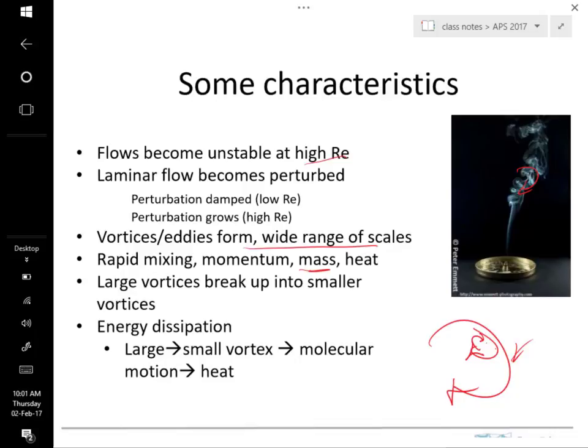And so what you have then is, under laminar conditions, the energy is being consumed at the molecular scale from molecules sliding past one another. But then as you introduce turbulence, you have this whole cascade of scales from large eddies to smaller ones, on down to the molecular scale, where it's just really dissipation by viscosity. Okay? So that's the conceptual model.